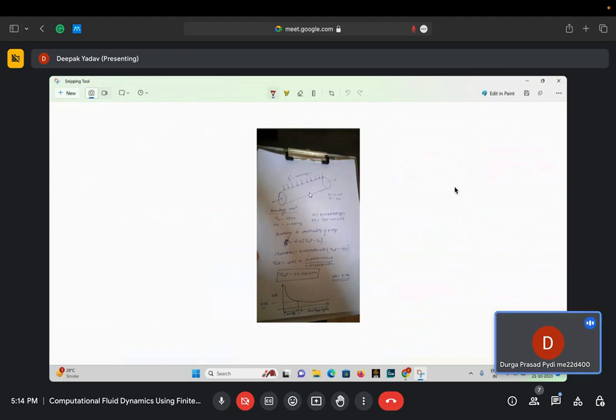So you already done the simulation in ANSYS, right? Yes, I done the simulation, and meshing also performed in Fluent Meshing such that orthogonal quality is greater than 0.1 and skewness less than 0.1. So then there is an option where you can actually get this expression. Can you open the simulation, or will it take time?